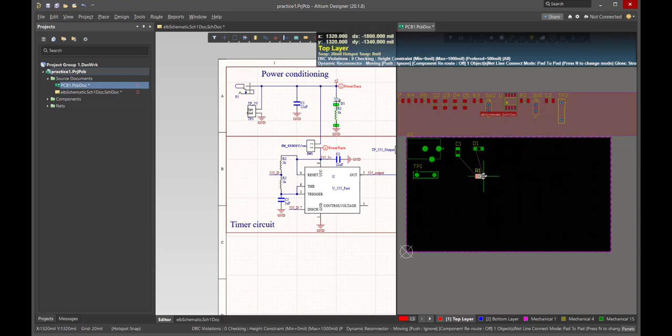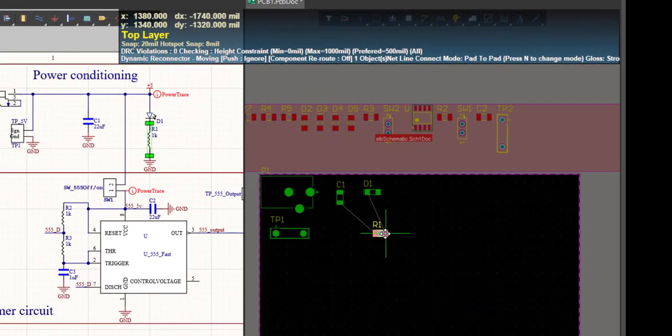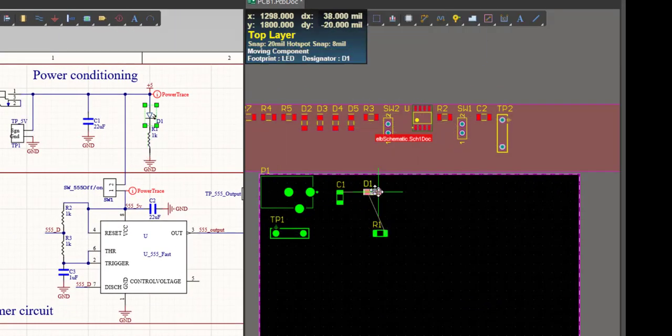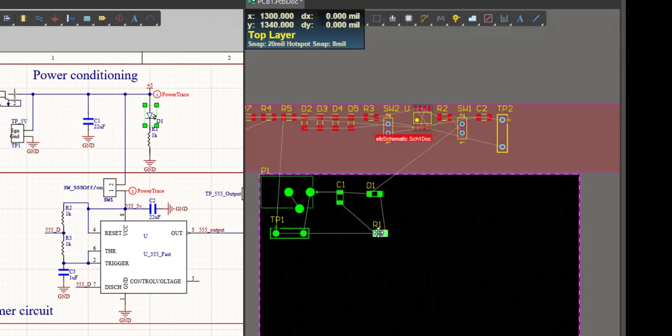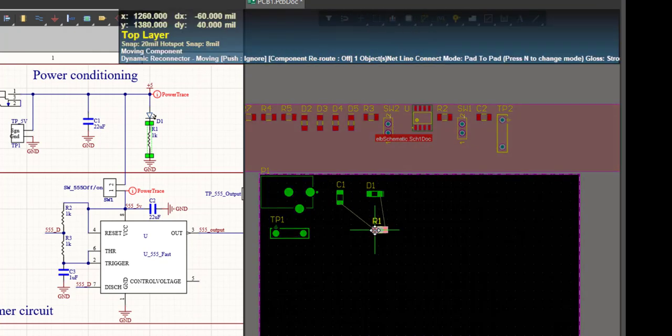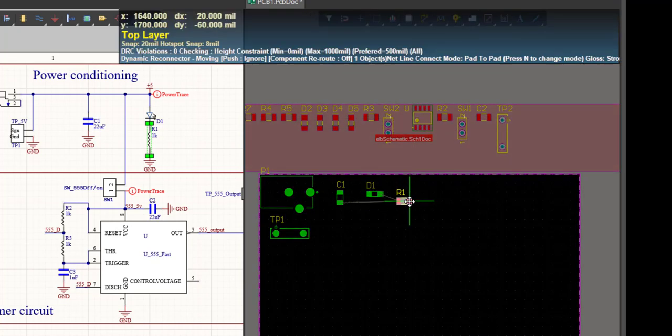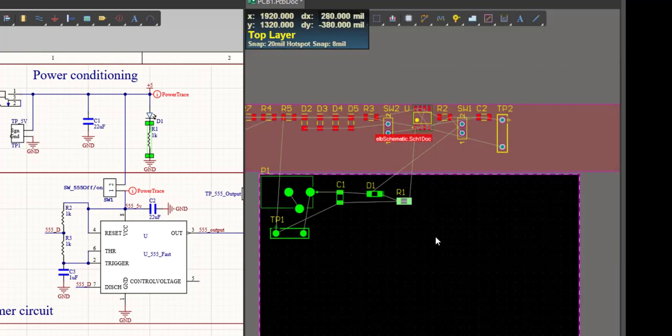And this is where thinking about the connectivity is going to be important. So you'll notice the R and the diode orientation. I really want to reverse the direction of the diode. And that way, if I reverse the direction of the resistor, hey, now I've got the connections between the diode and the resistor closely spaced. Now, again, my strong point is not neatness. And while it's not essential for the functionality, a neat board, number one, it looks nice, and number two, it sometimes is easier to debug.